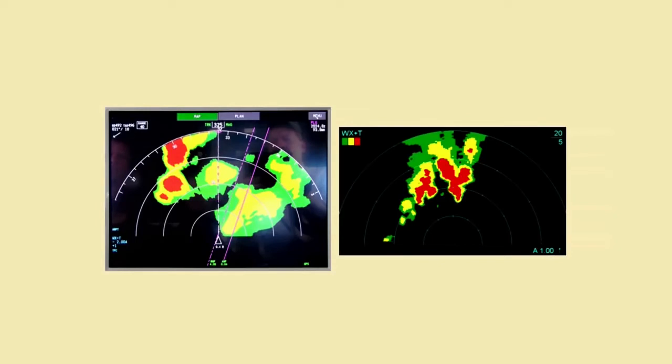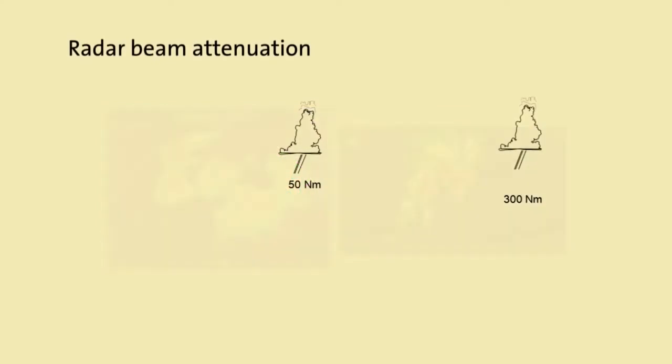By way of contrast, the irregularity of these cells indicates significant shear activity, and the very steep gradient between the colors is typical of very strong convective lift. Once again, these U-shaped areas represent possible hail shafts. With regard to these cells, green is a good color to avoid by a wide margin. Increase in green returns will also occur as weather nears the aircraft.